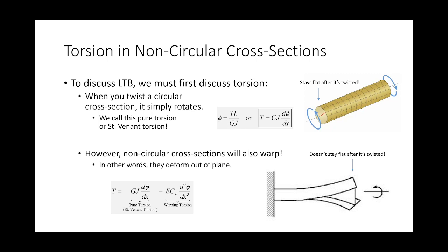And to be clear, in the land of engineering, we typically try and limit torsion to being applied to circular cross sections, okay? If you don't believe me, go look at any element in a car that's being twisted, right? We're talking about camshafts, we're talking about the steering column, axle, anything that's being twisted. Look at the actual mechanical element that's being twisted, and it's circular, okay? There is a reason for that.